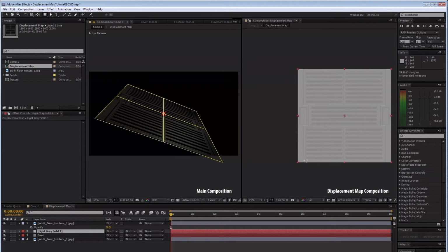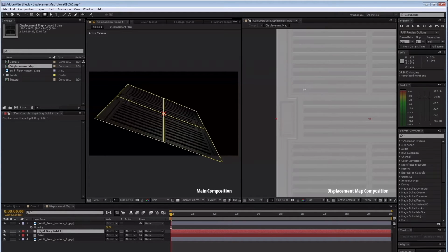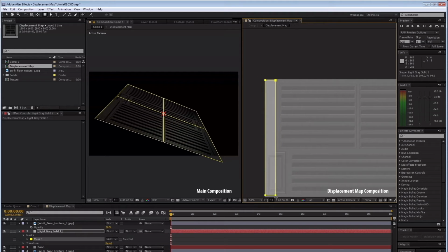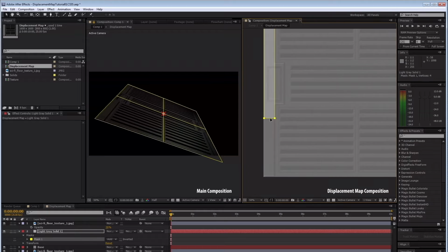Now you can see that there should be a bevel around the shape here, and I'll show you how you can easily make that. Just go in the middle of this bevel, and you can draw a first shape. Gotta extend this all the way down here, and then I'm just going to add some points.